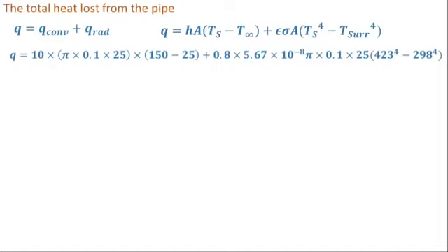It is shown in this equation that I have put the value of temperature in Kelvin when I am going to solve radiation heat transfer. As we have discussed in lecture 1 when we were learning the radiation, in order to solve the radiation heat transfer equation, we should put the value of temperature in Kelvin scale.